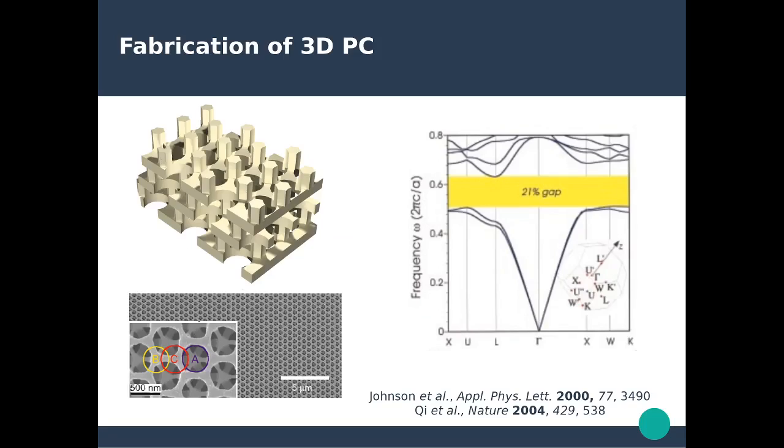So this is the resulting photonic crystal you obtain with this particular fabrication technique. You see that you have those three circular holes that are offset with respect to each other, inside those silicon layers. And in between those silicon layers, you have those silicon rods that we just talked about. This is a SEM image of such a structure. You can achieve very large scale for those structures, tens of microns in size. This is a close-up view showing those circular holes, in successive layers. You can see the underneath layers with the holes that are offset with respect to the first layer.